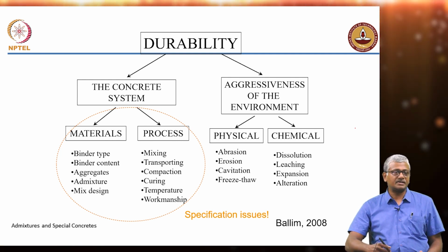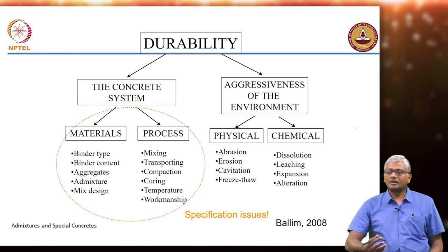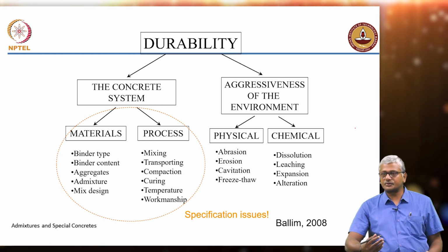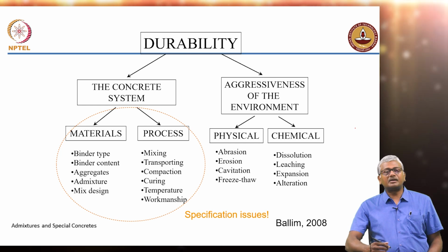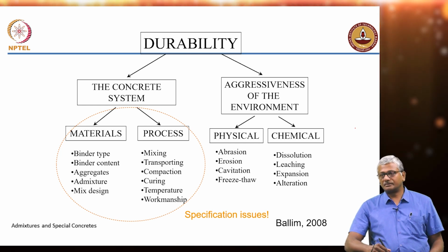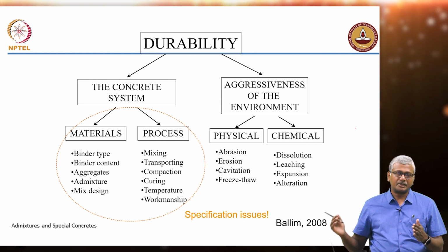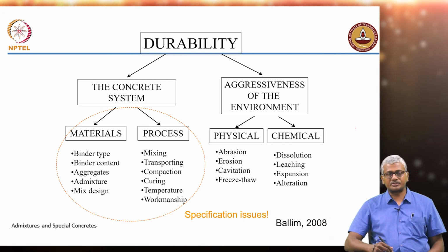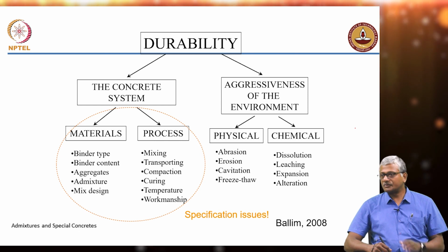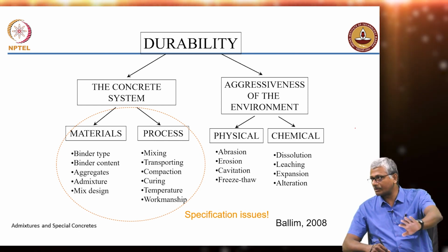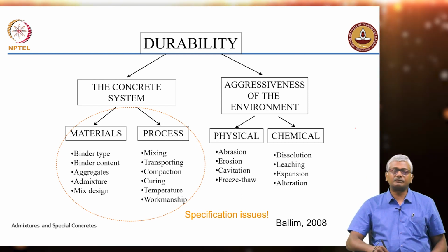Chennai is a coastal city, so you expect corrosion, right. Corrosion of reinforcement is going to be primarily driven by chlorides, which are present in the seawater or, in zones slightly away from the coast, in the airborne salts that are taken up by the winds, which will deposit the chlorides into the concrete, and that will ultimately drive the corrosion of the steel.